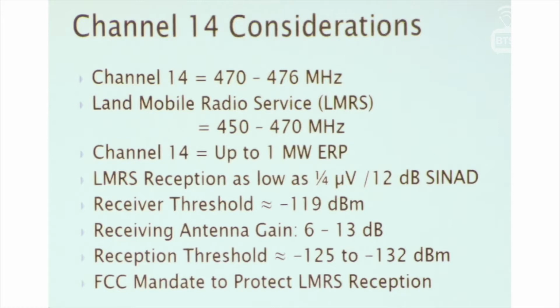So there is no guard band between a service that can be delivering 1 megawatt starting at 470.001 megahertz, and another service that can be looking for a 1/4 microvolt signal at 469.9995 megahertz. And yet we have to provide protection for that. So this gets to be a bit dicey.